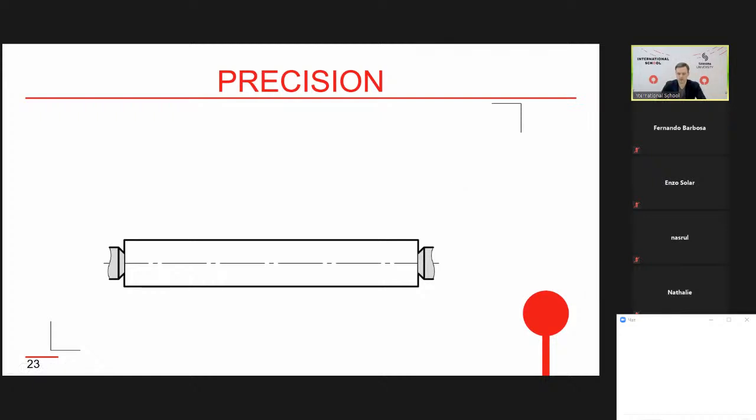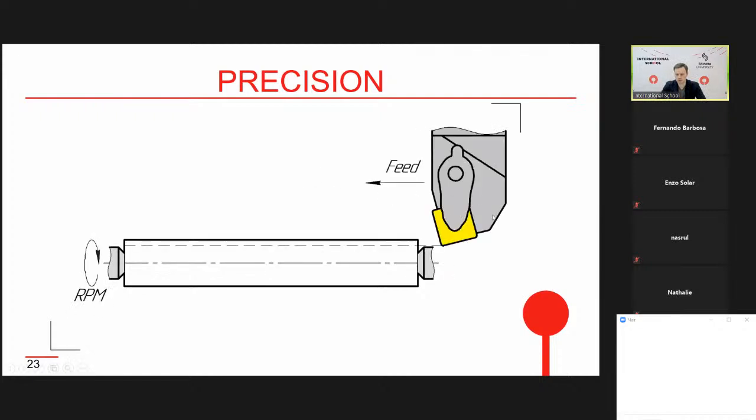These clamping devices are called centers, and the next picture shows us a clamped workpiece. So the workpiece is clamped, and now the tool goes to the diameter of cutting. The diameter of cutting and also the path of the cutting tool is shown by this dashed line. So this is the trajectory of movement of the cutting tool. This is the direction of movement. It is called feed direction. And also it's a turning process. That's why the workpiece rotates. RPM, rotations per minute, which means that the workpiece rotates around its axis.